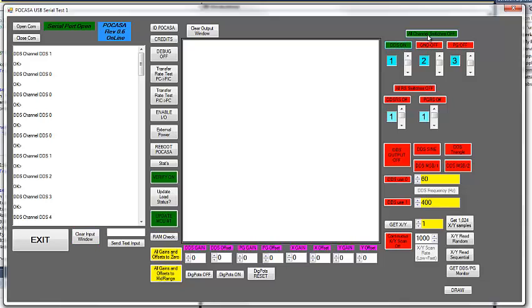You can turn them on, turn them off. You turn them all on. You hit this button to turn them all off real quick. Down here, the RS switches, that's the source resistance. The lower the resistance, the more current you can push through the circuit at a given voltage. Same thing here, turn them on, turn them all off. They go to really high impedance.